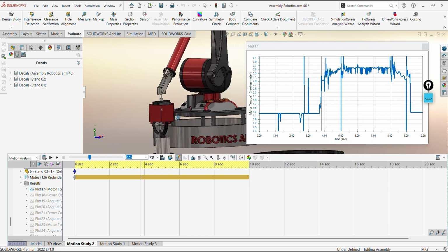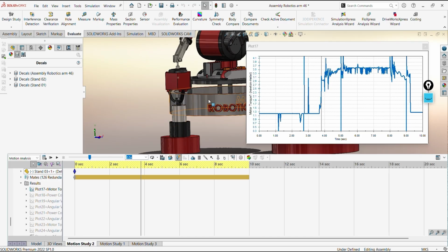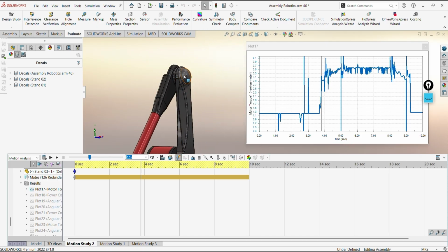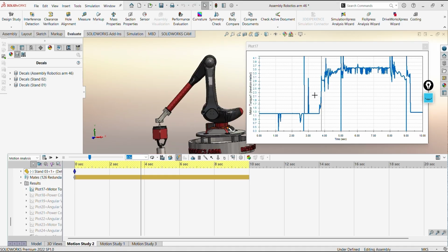And now, in addition to the jaw and the arm, the aluminium weight is also contributing the torque at the arm. That is why the torque required by the base motor has now increased to 3 Newton meter at the fourth second. Before moving any forward in the graph, as you know that torque is load times distance, and we are calculating the torque at this point. Let's say the distance between the weight of the aluminium and the point where we are calculating the torque is R.